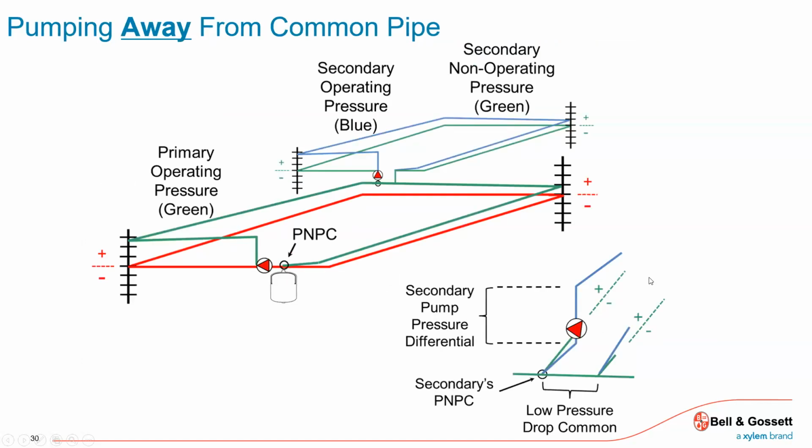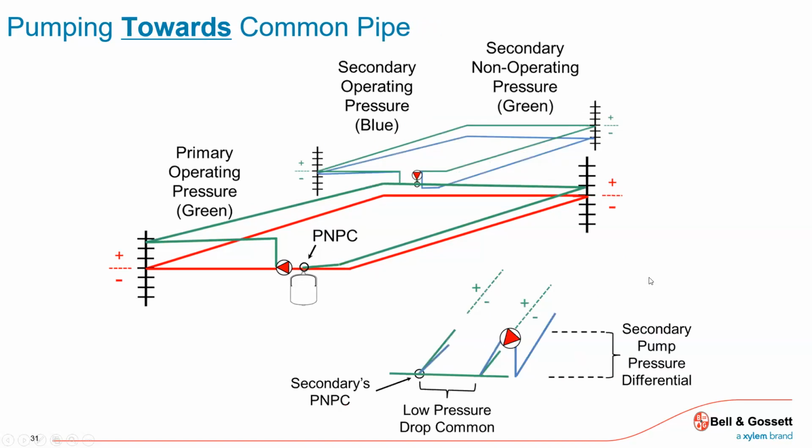When you get into primary, secondary, all it's talking about is, hey, wherever that loop is, wherever your expansion tank is, and that point of no pressure change, when you add your secondary circuits, make sure you're pumping into the secondary circuit so that you'll get the same benefits that your primary pump does by pumping away from the expansion tank. So it's just adding pressure into pressure.